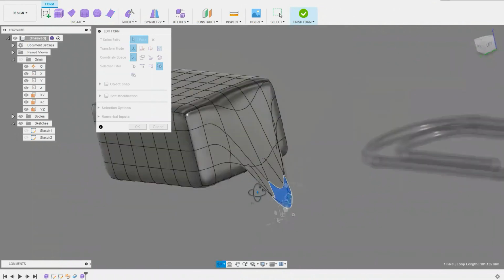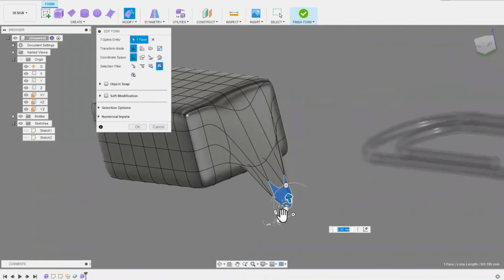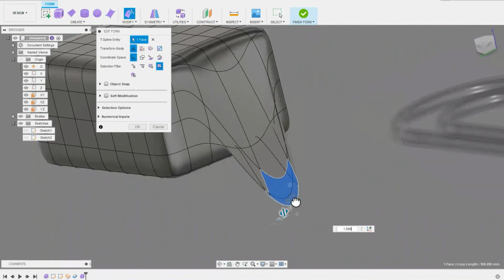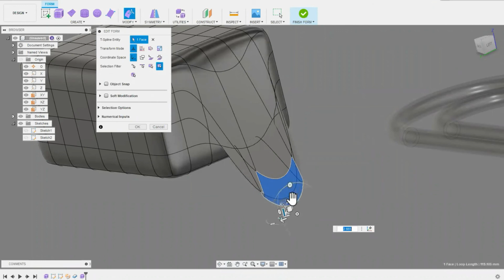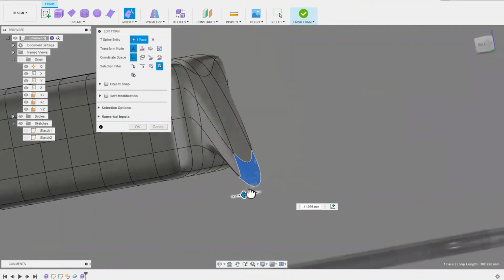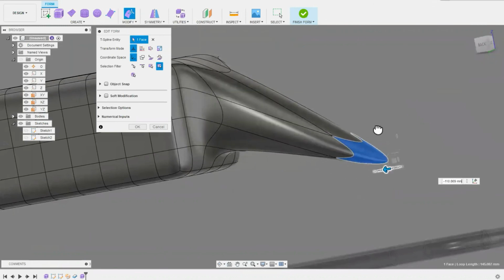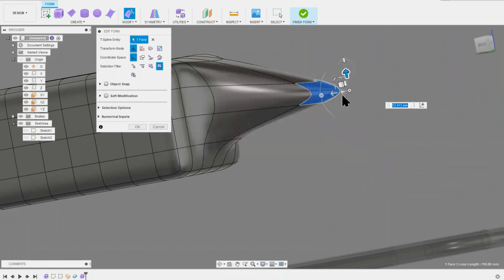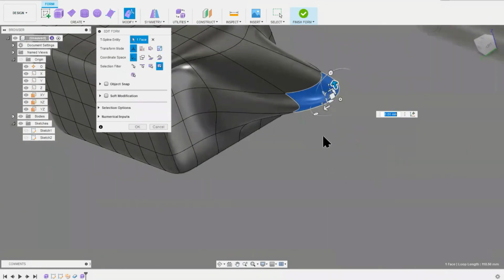I'm dragging that face in a specific direction. And again, I'll grab this. We can also twist it by selecting an axis line there. So we've got quite a number of tools and options for creating a drag position. If I wanted to drag down this way, we simply click that arrow and allow our model to move. So it's a very flexible and free-form method of modeling.